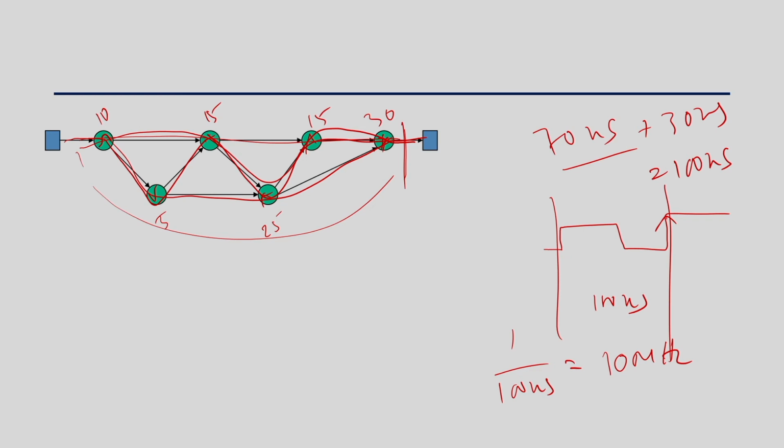Okay. So, what does retiming do? It tries to move the registers, or the sequential elements, of the design in such a way that it does not change the functionality of the design, it does not change the latency of the design, but it actually reduces the combinational path length. Okay. I will just give you an example.